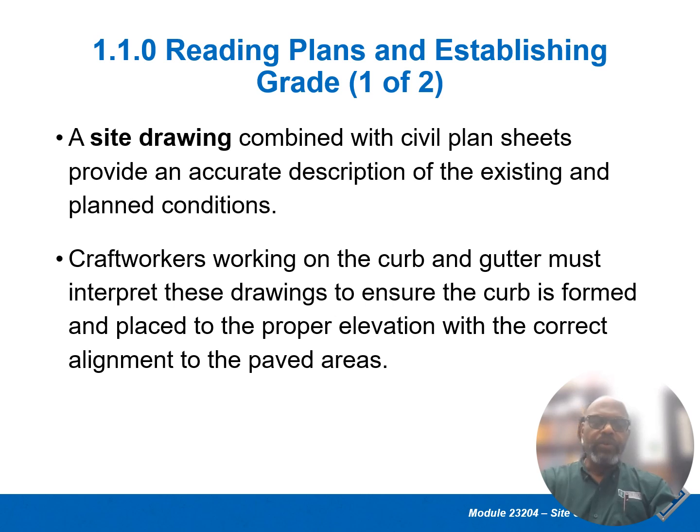In other words, they would give you the topographical dimensions of where the curbs need to be installed on the landscape. Craft workers working on the curb and gutters must interpret these drawings to ensure that the curb is formed and placed to the proper elevation with the correct alignment to the paved areas. It would be pretty bad if you set the curb and it's not lining up with the street. Typically the curbs go in first and then they pave.